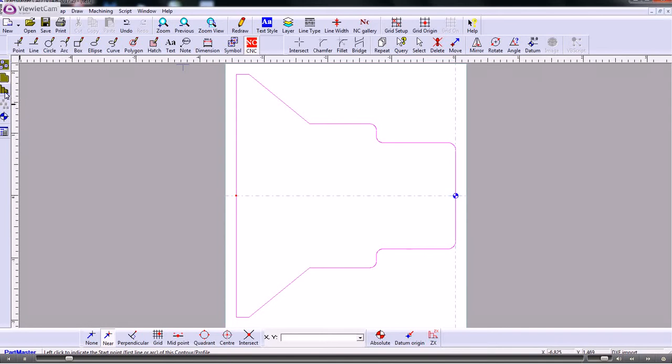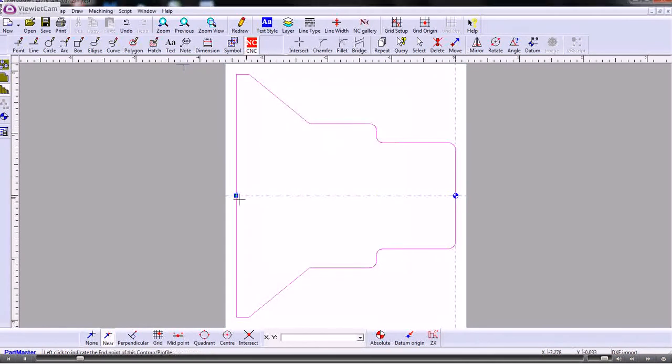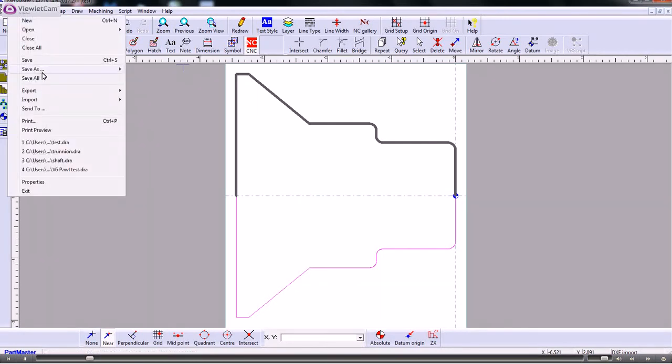So what we need to do is to produce this thing called a profile. The profile will start from the front. Let's give it a width just so that I can see it. It's not an enclosed shape, so I need to give it an endpoint. And that just checks that the geometry is contiguous and that there are no gaps or overshoots or anything like that. So that's safe to take through into the machining software.